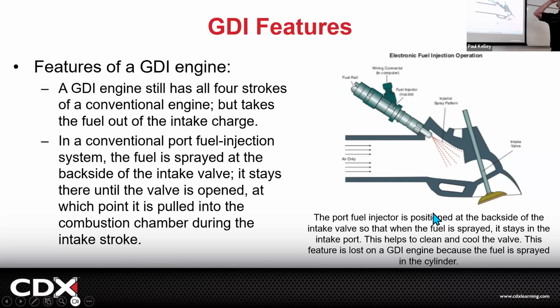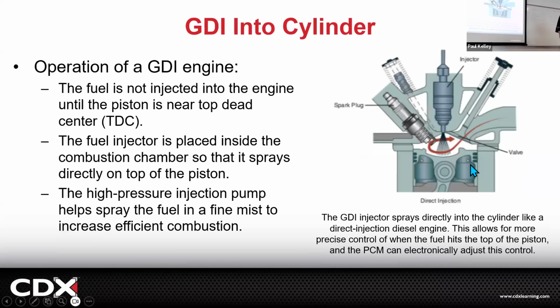If you go back to carbureted, some of that fuel is going to get burned, and some of it's going to be smelled. The old cars smell different. They're like, yeah, I can smell that car. Yeah, because there's fuel evaporating coming out of the intake because you didn't even burn all of it. You burnt some of it, right? The port fuel car is going to be much more refined. And this is going to be a huge step above that, right?